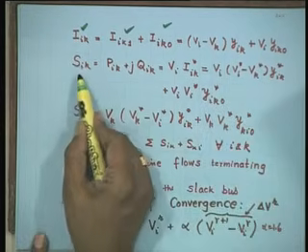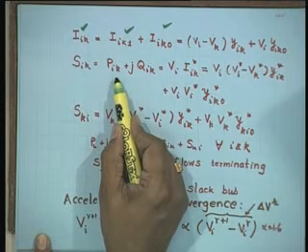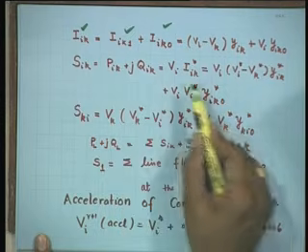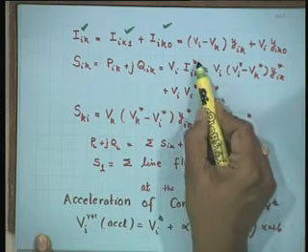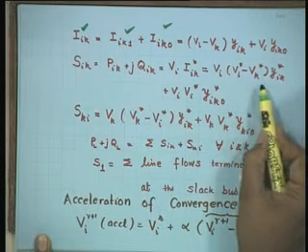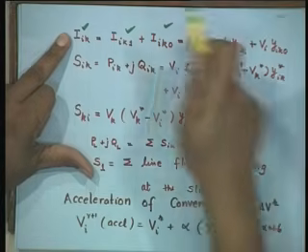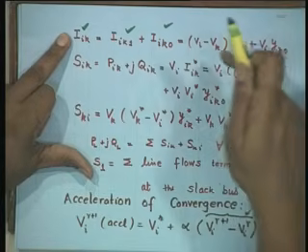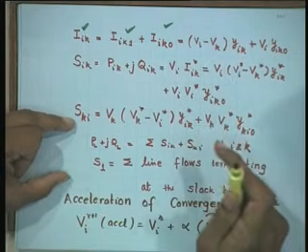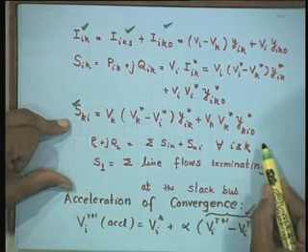Once you do that, you know the line flow Sik, which is real power flow plus j reactive power flow. That is Vi Iik star. We have just found Iik. Substitute. Star means you have to conjugate everything that has come here, so make it star, star, star wherever there is no star. Similarly, find Ski, the same way.